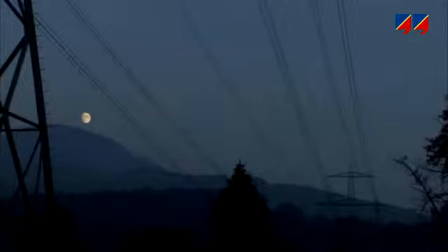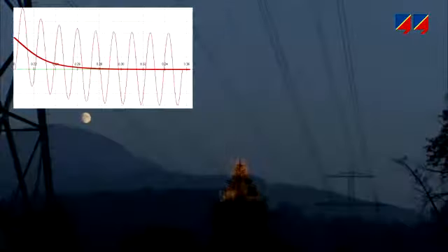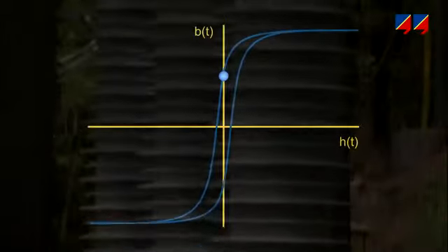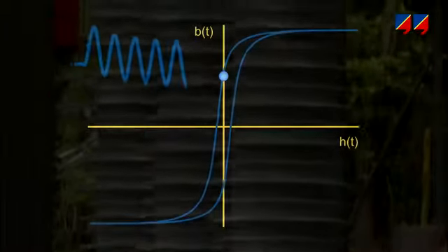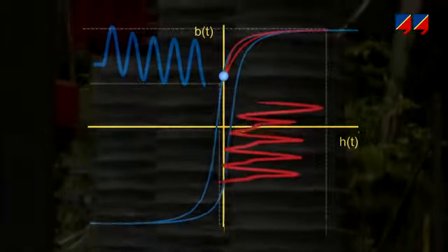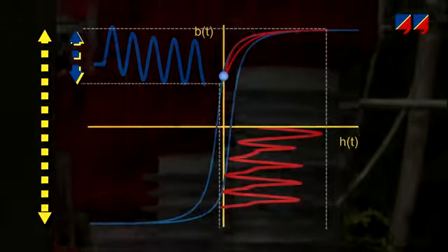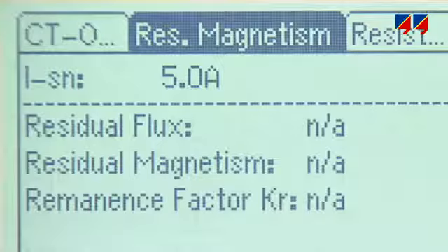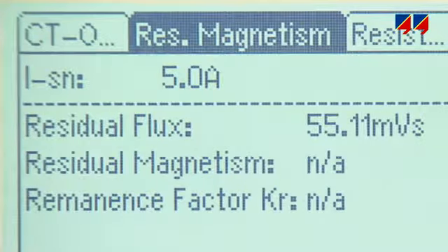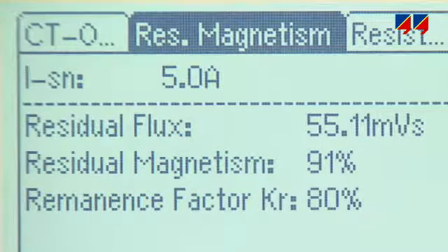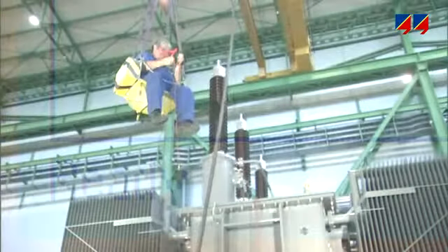After short circuit faults involving high DC components, a CT may have magnetic remanence, particularly in closed iron cores. During the next fault, this remanence can cause the CT to saturate at much lower short circuit currents than calculated. CT Analyzer's Remalizer function can determine a CT core's magnetic remanence, helping to analyze unexpected relay behavior and subsequently to remove it by demagnetizing the core.